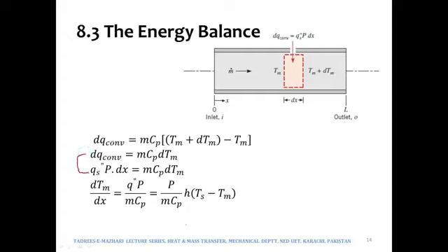Q can then be written in this form, because it is written in the form of heat flux times area. So q double dash is the heat flux, times area. Area would be the perimeter times dx. If you remember, we had done the same kind of thing when we started the topic of fins. So that would be the area, which is also mentioned over here as well. And the right hand side remains unchanged.